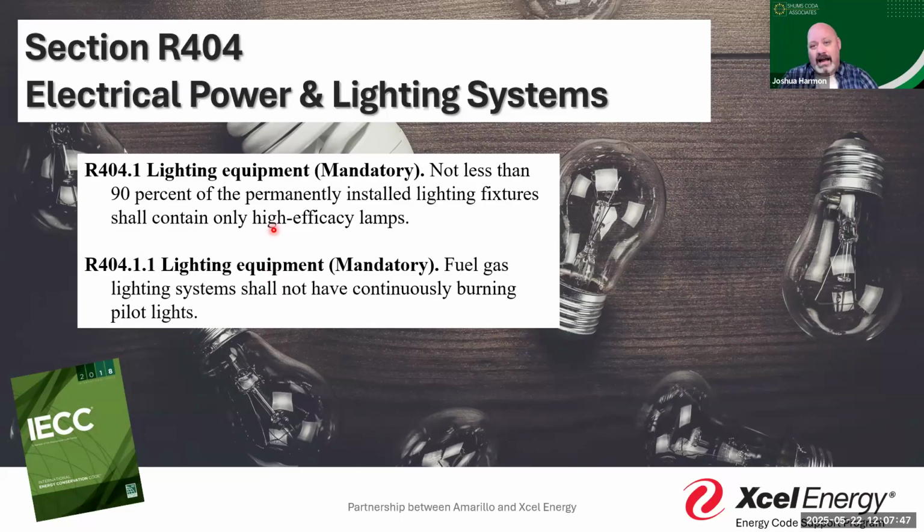The only other requirement in the energy code for the 15 and the 18 is that if we're going to have fuel gas fired lighting systems, they can't have a continuously burning pilot light, right? So if I decide I want a real flame out by my patio deck, I actually have to have a connected firing mechanism. I can't just have that pilot light running constantly, because that's using energy when I'm not using the light. That's the rationale behind where the energy code was going.